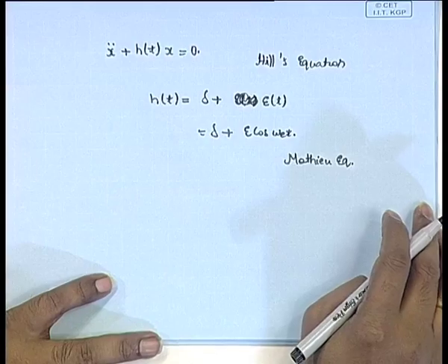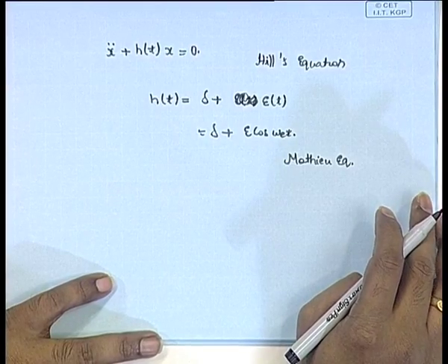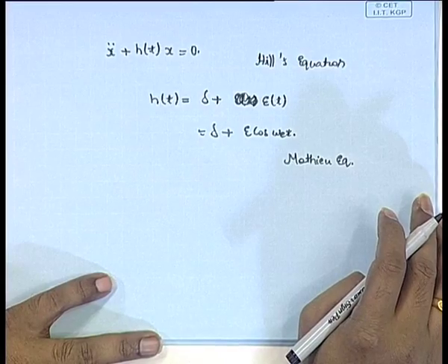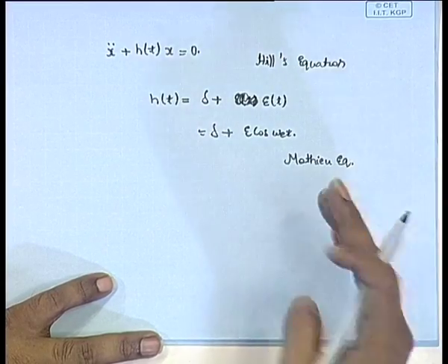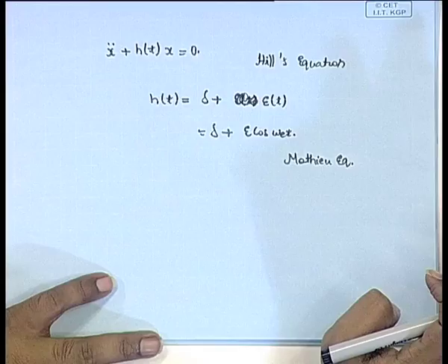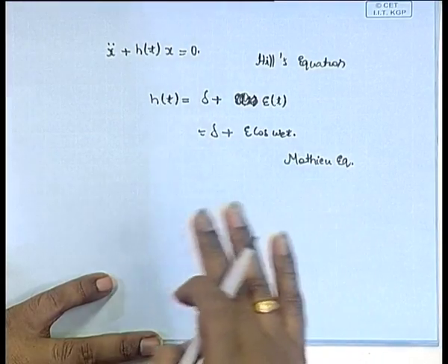This is the equation that we just mentioned. This is the equation that represents the ship's motion, or the heel of the ship on the wave. So, if you have a wave propagating and you have a ship on it, then the equation of motion of the ship, that heel motion phi, is always given by the Mathieu equation.